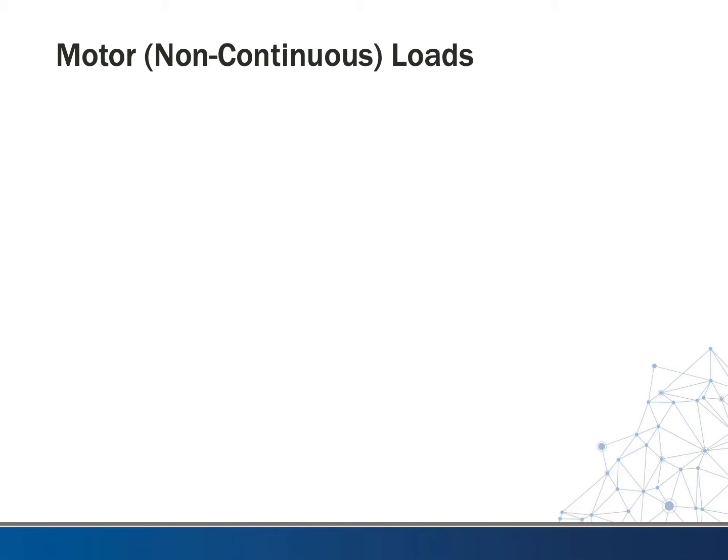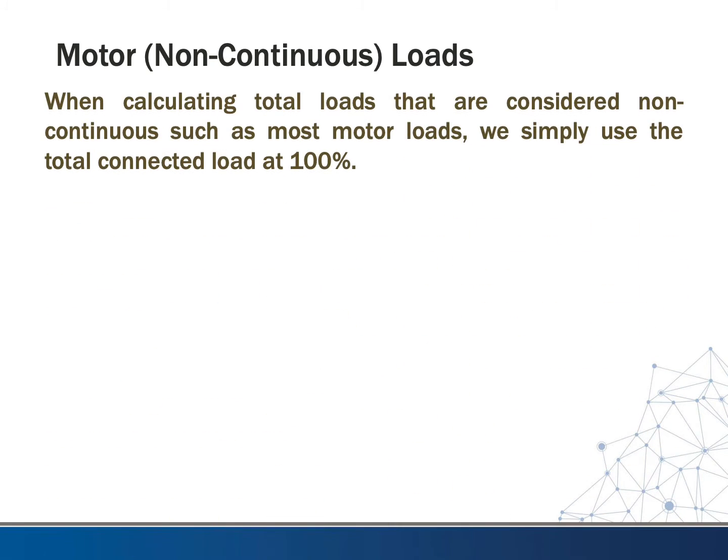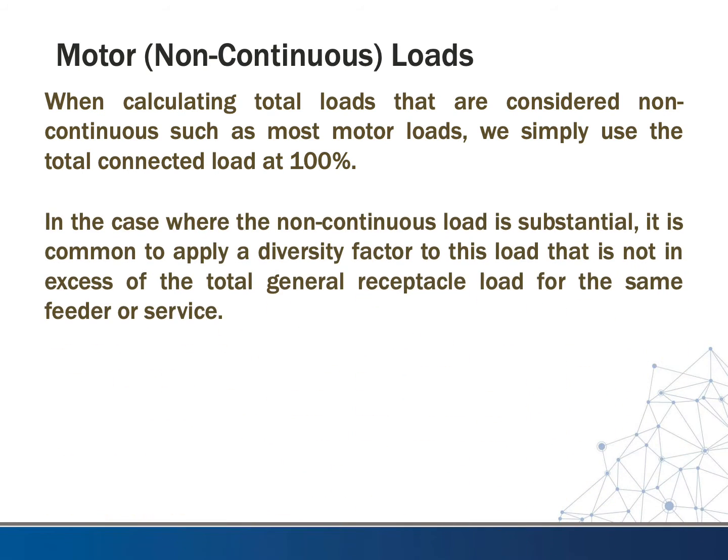Motor loads, again, we're considering these non-continuous motor loads. Again, when calculating total loads that are considered non-continuous, such as motor loads, we simply use the total connected load at 100%.